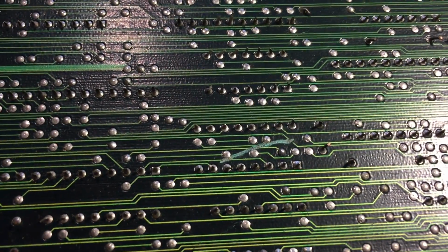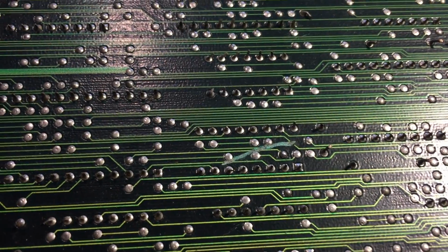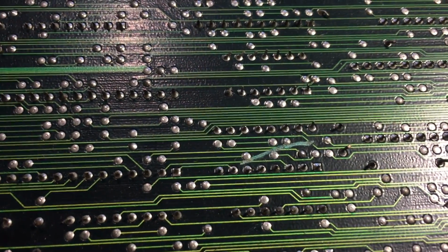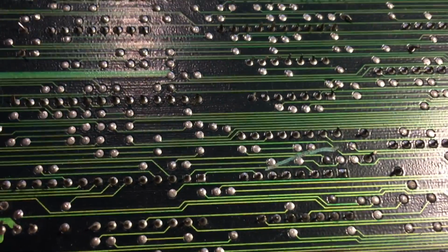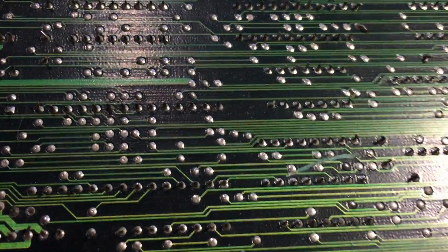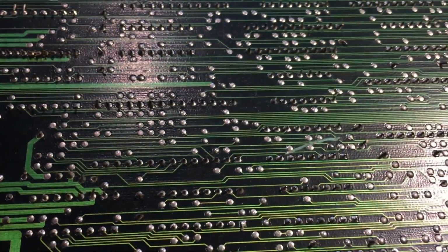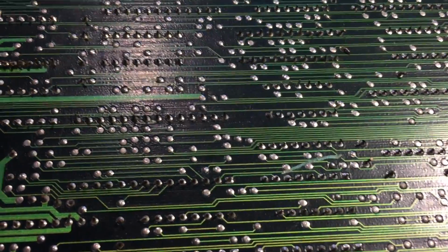This is under a counter IC for the voice output, so I suspect this will not fix the connection between the main CPU and the sound CPU. I may just have to run a patch wire for that directly rather than figuring out where the original break is. But let's solder some wires on here and see where we get.